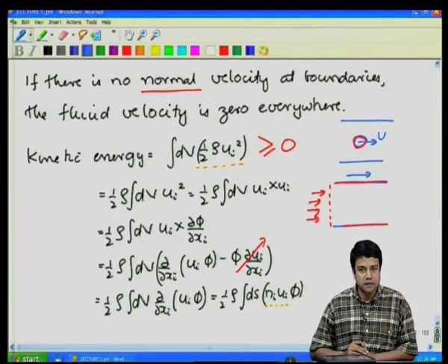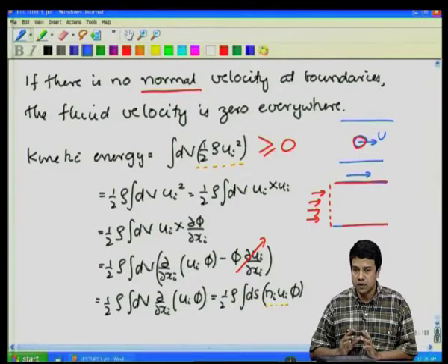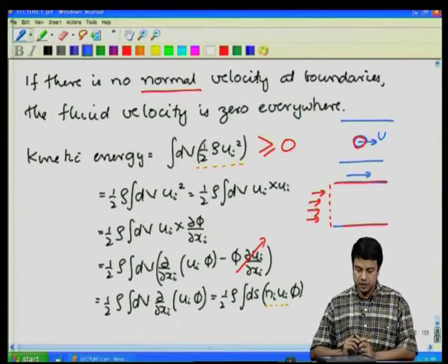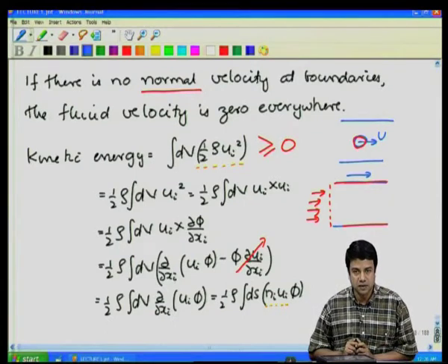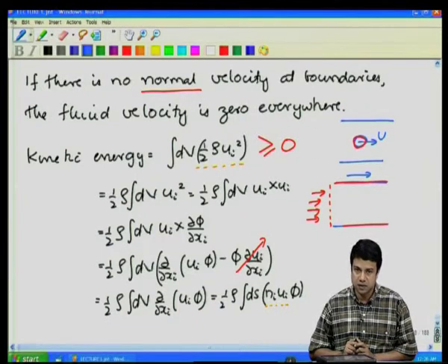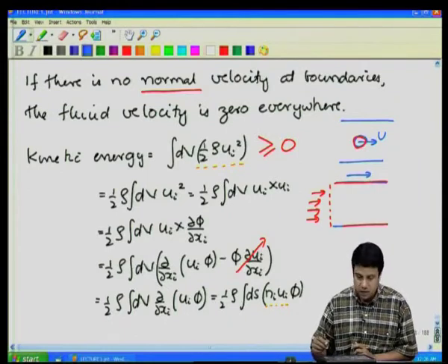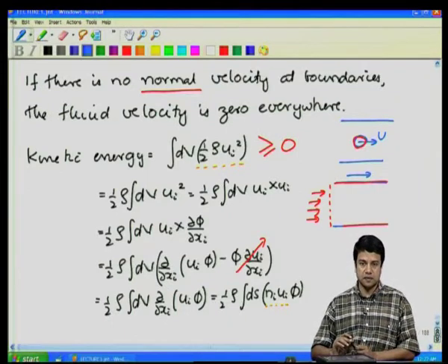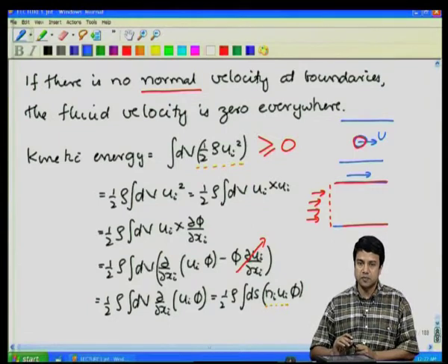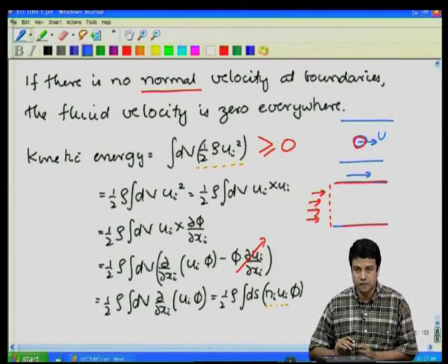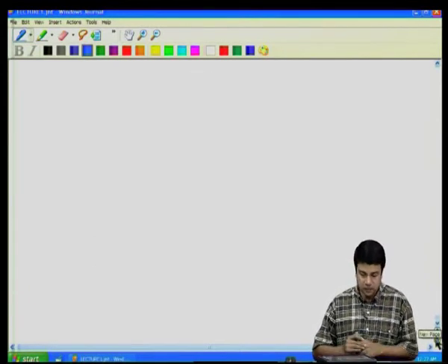One could derive other relationships. When we looked at viscous flows, I said the equations are linear, and because the equations are linear, the solutions exist and they are unique. That was because the Stokes flows are linear. The pressure and the stresses are both linear in the velocity. In this case, the pressure is a nonlinear function of the velocity, but still it is possible to show that the solution is unique for potential flow. So, we will briefly look at the uniqueness of the solution.